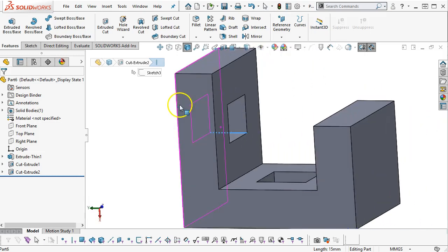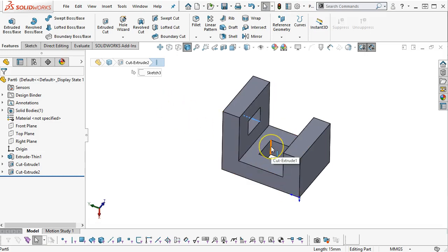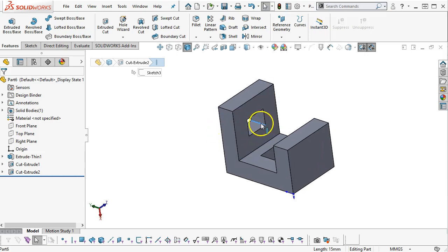If I can put even a minimal amount of radius in there, it's going to help with the manufacturing process. We're going to be able to wire EDM, leave maybe 5/1000ths of radius in the corner for the wire, but wiring this, just like we saw the extrude cutting into this base material, the wire is going to do the same thing. It's going to try and come around.